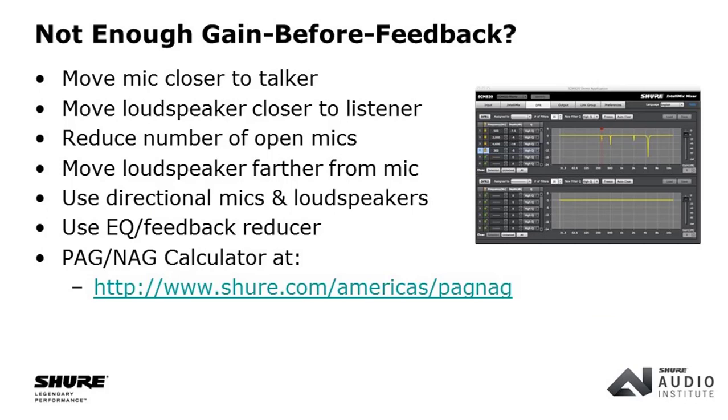You can either move the microphone closer to the talker or the speaker closer to the listener, because then you don't have to turn everything up so much, and that reduces feedback. You can reduce the number of open mics, like we talked about. You can move the loudspeaker farther away from the microphone if you want to. That always helps too. Using directional microphones and loudspeakers helps, but it's not like a night and day difference. It's usually something you're probably doing already anyway.